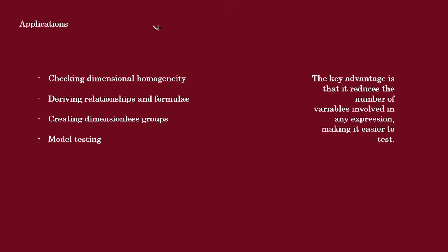So it helps us to say that, let's say we have a formula, y is equal to a plus bk plus root c, okay? Dimensional homogeneity tells us that every term in this expression, since it's a sum of different products, should end up with the same units, same dimensions. So let's say the dimensions of a are ml, dimensions of bk should also be ml, and dimensions of root c should equally be ml for the principle of dimensional homogeneity to hold. We'll definitely get more in-depth into this in the next video, but that's just for theory purposes.